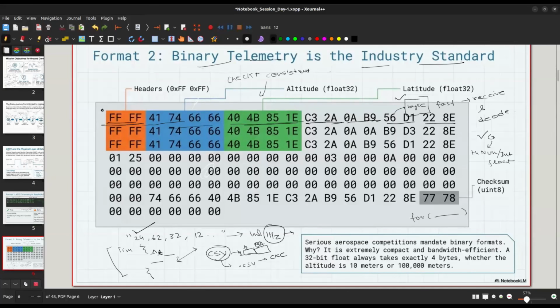Run a loop that says whenever you see this kind of format, FF, just continue, this is a new string. Let me tell you what happened in our case. This was the ground control station, this was the telemetry that we received. There was no header, we just received the values from here to here. In between there was some kind of a transmission loss, so we did not receive these values. Instead we received the values from the next string, and we assumed the 0000000 is going to be here, and the D12283 is going to be here. Just because we missed some packets, we assumed that the original values were of the next packet.